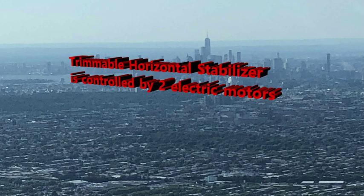Trimmable horizontal stabilizer control. Here you have 2 electrical motors that are responsible for the actuation of the THS. Okay, and one is connected to Prim 3 and Sec 3, and then you have another motor that's connected to Prim 1 and Sec 1.